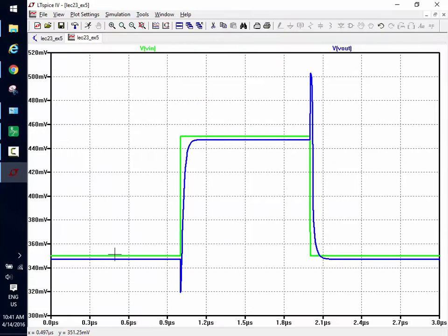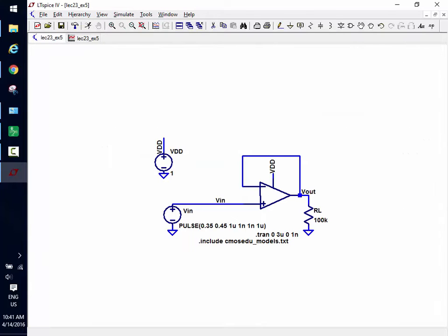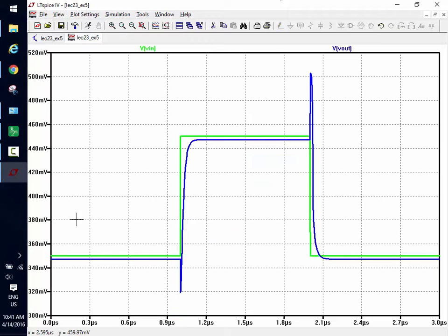We see the gain. How would I need to increase the gain if I want these to be tighter? I could go back and put 1 microamp in there, but it'll slow everything down. Does everybody see what I'm doing? Does everybody understand what's going on other than why is there a pulse here? How do I minimize this? All that stuff. Questions? What about if I put a capacitor there? Yeah, you can play around. I think I've given you enough.